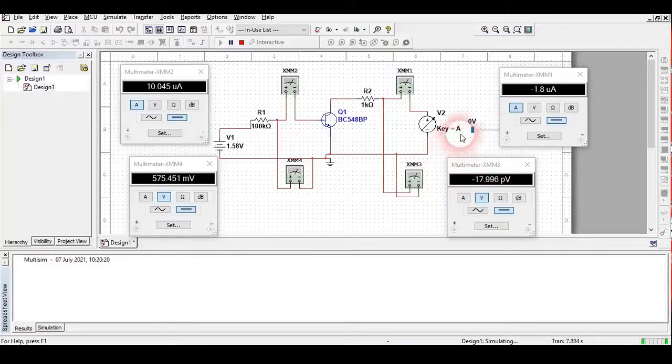So initially, just see what happens when we change the value of voltage here. When I change the voltage, just see the current here decreases. Firstly it decreased, and now it decreased to 9.773. If it had decreased very low, I wouldn't have considered it, but it has decreased somewhat. So again I have to make this current 10 microampere. So at 0.2 volt also I need to make this different, so for that I am again going to change this value of voltage.